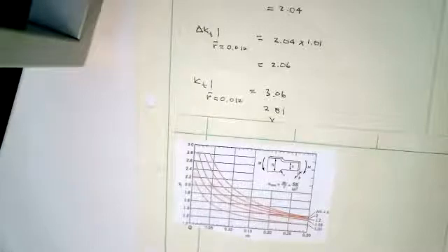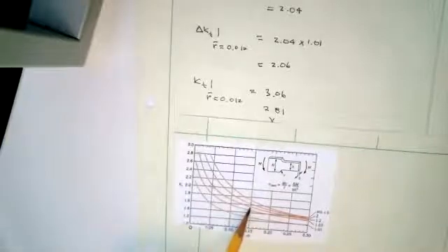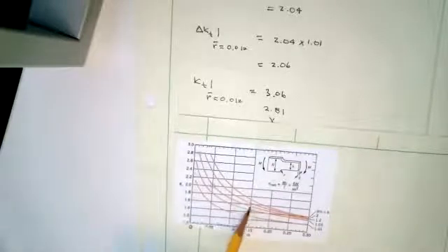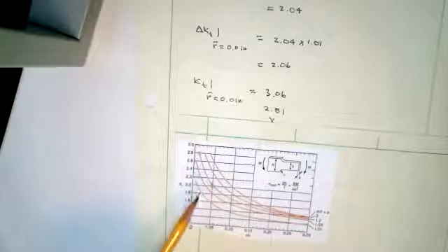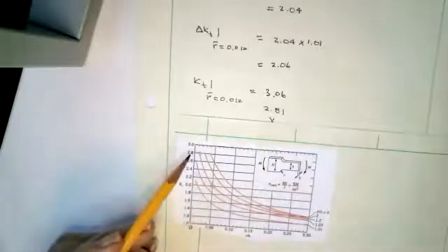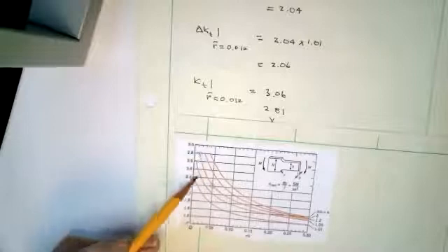There might be, okay? And we're going to start talking about finite elements. One way you could do this accurately would be to do your own finite element analysis if you had the small radii. Okay? But what you're going to find is that this approximation, this 1 upon the delta KT being proportional to 1 upon the square root of R bar, works better and better the smaller the radii are. It doesn't work so well if I was to do it back here and try and get this value from this value. Okay? But once you start getting smaller, it works pretty well. But yes, whoever put this chart together, this is the values they had.